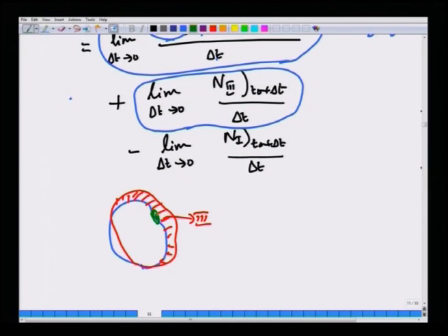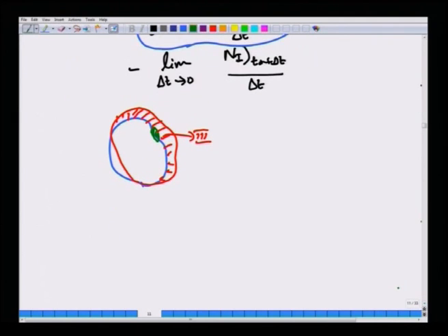The control mass is moving because if you take a patch of surface on the CV, that patch is moving to a newer region, because the fluid on the surface of the CV has some normal velocity, a component of velocity in the normal direction.